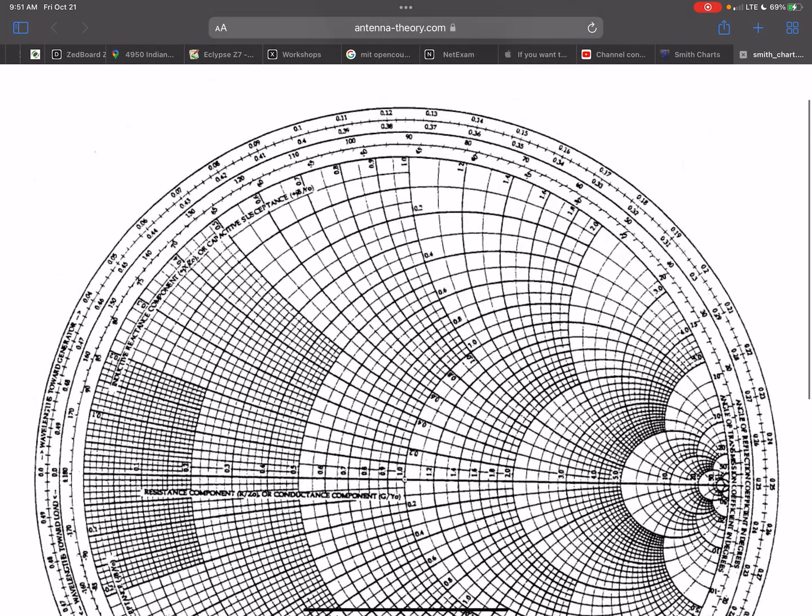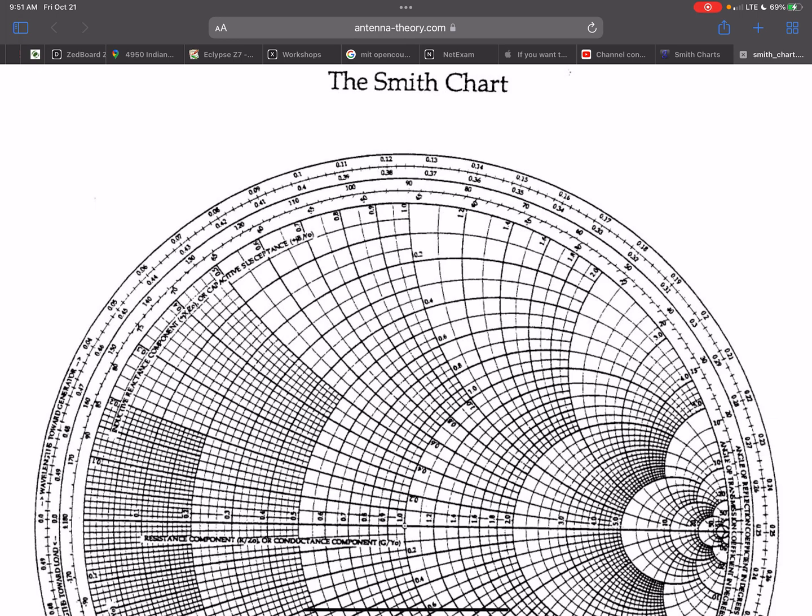And there are different measurement tools. If you actually were going to measure the input impedance of a transmission line, what would you do? It's not easy. What people do is make a sample of that transmission line, say on a printed circuit board, to see what the impedance looks like along that line.